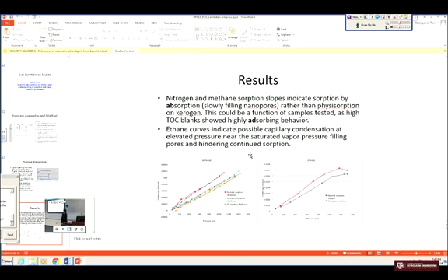Number one, look at the pressure. The pressure down here is up to about 1,500 psi. Pretty high pressure. This is methane. So what we're finding, quite consistently, is that there is no such thing as Langmuir adsorption for methane. It's a pretty linear adsorption. This is something we found with several types of cores, both Montney and Barnett. I'm showing here only the Barnett. On the left, this is the methane. There is nothing but consistently a linear adsorption, no matter what.